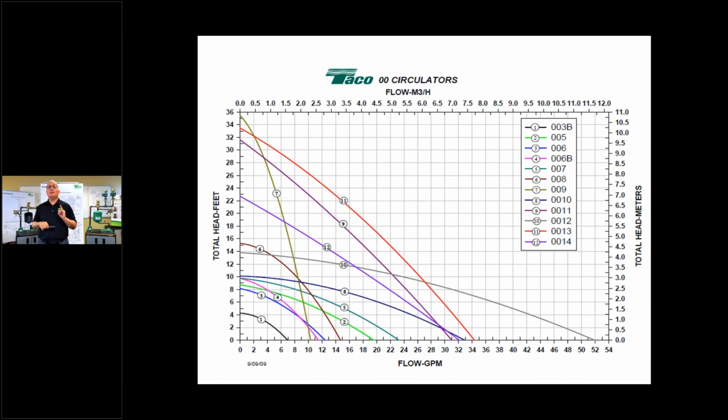Now, it comes in 2 configurations. It comes with a 2-bolt and a 4-bolt configuration on the flange. So if I'm thinking more on the service side, probably the 4-bolt might be a good option for you. This way, when you get to the job, you have options in positioning that circulator when you're on the job. Okay. If I was doing a lot of new installs, 2-bolt flange would probably be something you go to. They're both the same price.